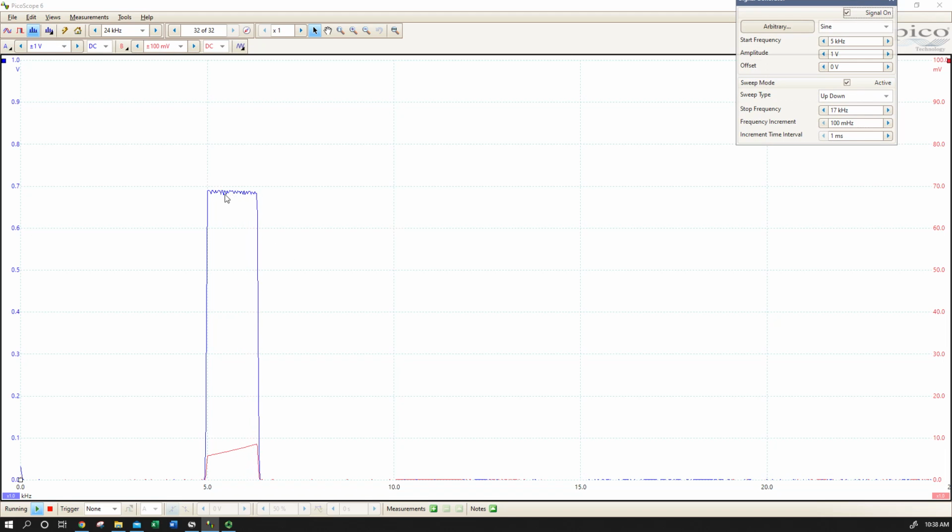And so you can see we're collecting, rather than having those kind of Gaussian plots that said, hey, here's the range of voltage amplitudes over this frequency window. We're only seeing the very top, because we're looking at snapshots of 0.1 hertz, and the Picoscope is collecting just the high point in that 0.1 hertz range. So it's kind of like we're drawing a line.